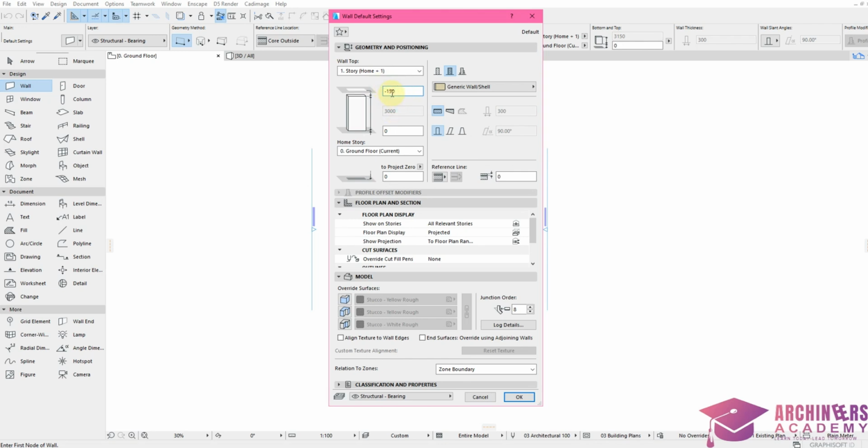Again, just use your hyphen key. Hyphen is the same thing as minus in Archicad. So just click minus 150. So it now subtracts. Archicad is proposing here that your height of wall is 3150. This is just a default setting of Archicad. Are you getting me? If you're using an older version like 16 or so, Archicad will propose a height of 2800 for you, and you're the one that will now increase it from 2800 to 3000.